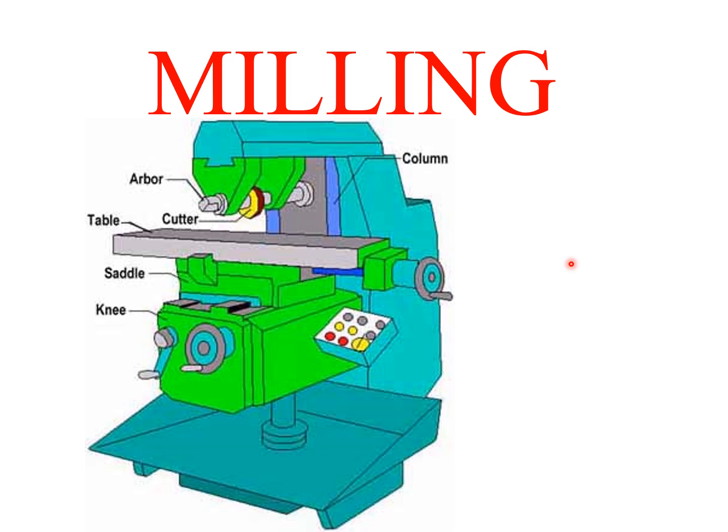As the milling cutter enters the workpiece, the cutting edges of the tool repeatedly cut into and exit from the material, shaving off chips from the workpiece in each pass. The cutting action is shear deformation. Material is pushed off the workpiece in tiny clumps that hang together to a greater or lesser extent, depending on the material, to form chips. This makes metal cutting somewhat different in its mechanics from slicing softer materials with a blade.